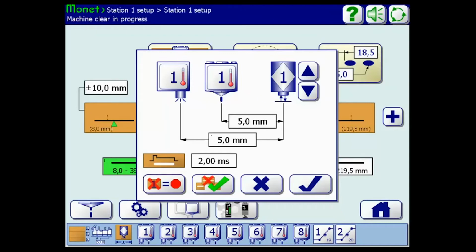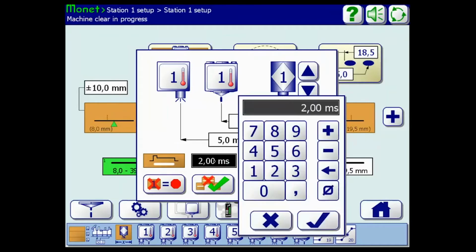Earlier, when we were looking at the LED screen, I think Alicia pointed out there's two different valve signals. There was a spike signal and a hold signal. And typically with cold glue extrusion valves, we use both of those signals. We spike the valve for a very short duration to open the plunger, to pull the plunger into the coil as quickly as possible. And then we don't require that higher voltage to hold the valve open. We can then drop it down.